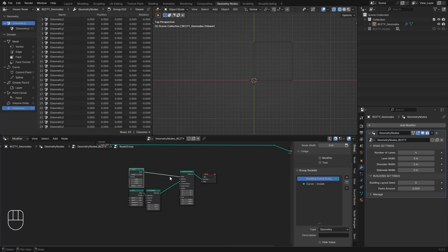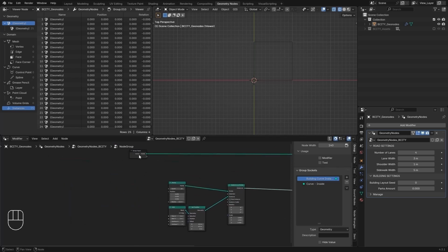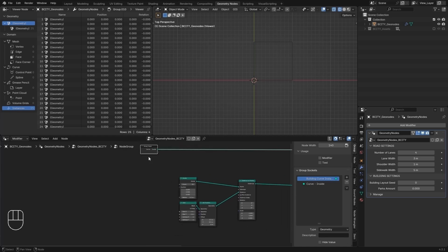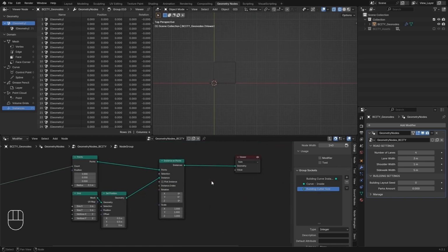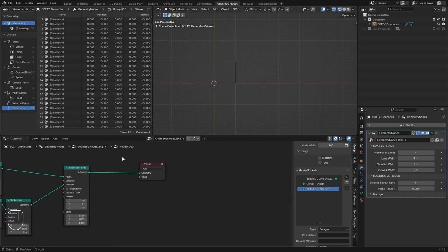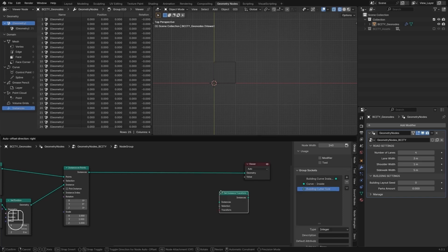This is a value we might want to control procedurally or parameterize outside of this node group. So the first thing I'll do now is duplicate the group input. Take the count value and expose it to the outer level of the group. I'll rename this to building cutter size. And next, we'll take our instances and shift them using the set instance transform node.